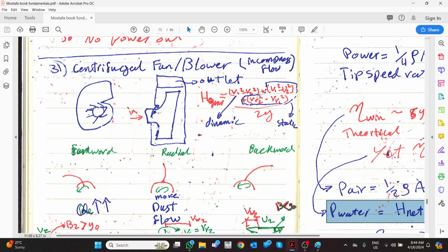I will give you an example. The maximum pressure you deal with for an AHU, how much? 500 Pascal? Okay, 1000 Pascal? 1500 Pascal? Okay, let's say 2000 Pascal. What is the pressure of the air? It is 10 to the power 5 Pascal.